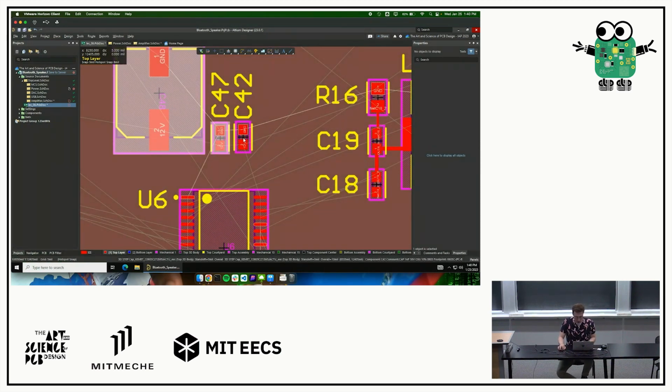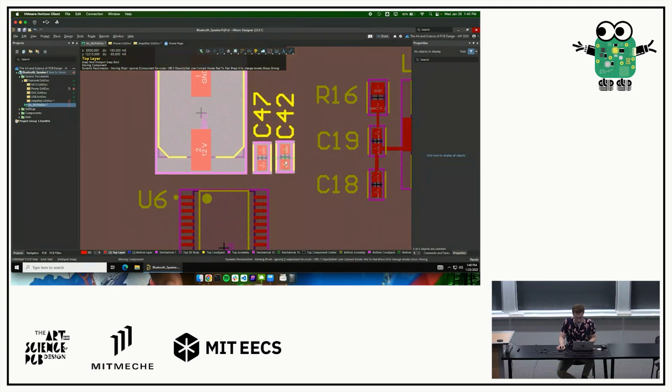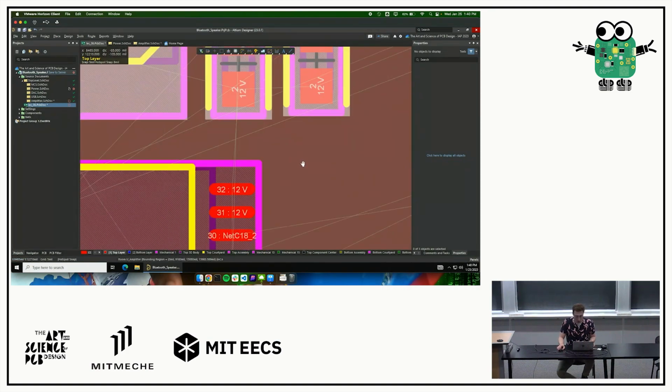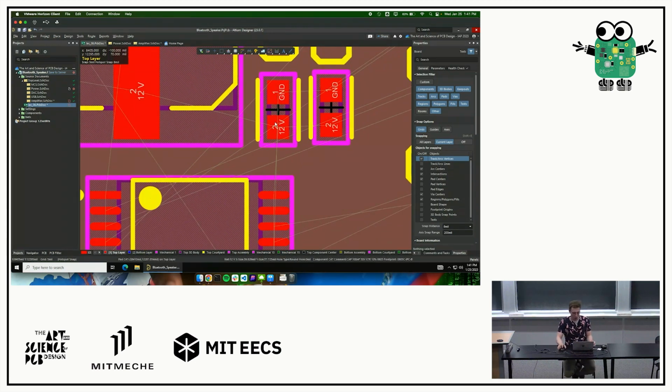Okay, so all of these are close together, and we can just route that down next to the chip itself, and excellent. So when we go to actually route this, let me see if I can figure out what the right shortcut is. Okay, it's a little weird because I'm on a Mac. But if you hit Control and then click the 12-volt thing here, it'll highlight everything that's 12 volts on the board. So you might just have to take my word for it for right now.